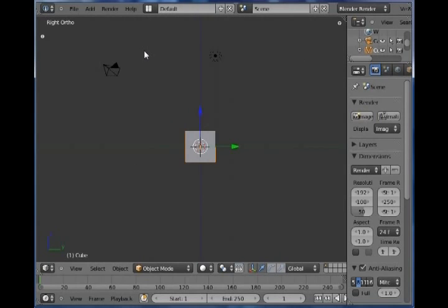orthographic drawing. If I want backwards views, for example, instead of a front view I want the back view, I can hold down my Control key when I hit the number 1, and I will now look at the back of the object. So, maneuvering around in 3D space, 7, 1, and 3, and of course 2, 4, 6, and 8 will rotate you around the views a little bit at a time, just like holding down your mouse wheel will rotate you.